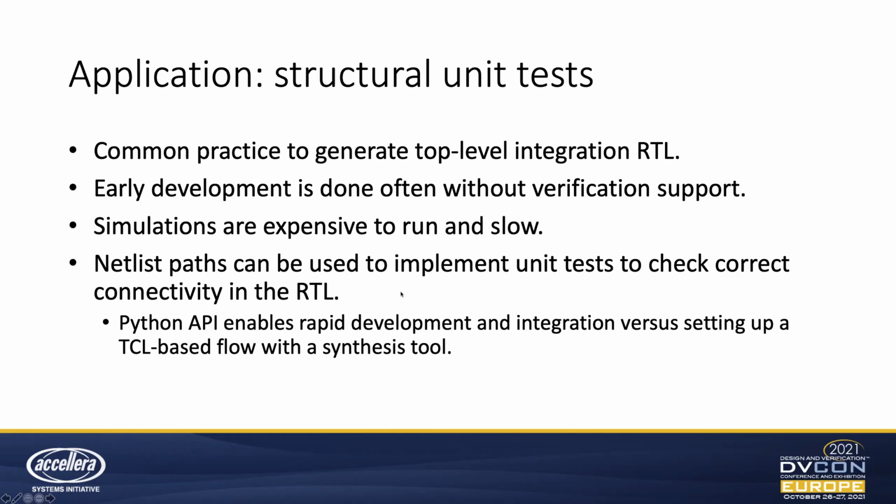This has picked up basic issues, and it has allowed us to run ahead of the verification and have confidence that all of these thousands of lines of auto-generated RTL are in fact connected in the right way. And as I've mentioned, because it's a Python API, and all of our infrastructure is based in Python, it was very quick to develop something like this.